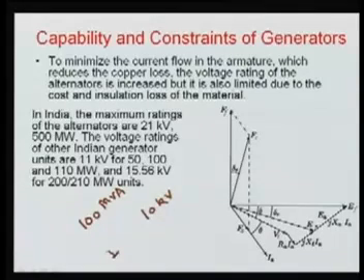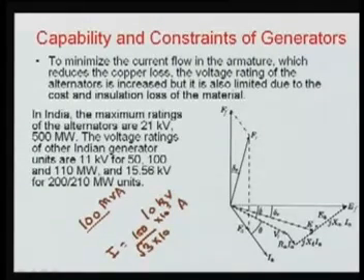Then, since it is three phase, the phase current will be 100 divided by root 3 times 10 kV. Here it is MVA, so it will be 10 to the power 3 ampere, or I can cancel this out, so it is kilo ampere. So you can see this many kilo amperes of current is flowing.